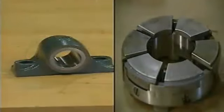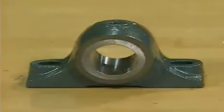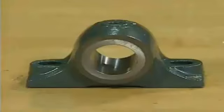Sliding surface bearings are often divided into two basic categories based on the type of load that specific bearings are generally designed to handle. The two categories are journal bearings and thrust bearings. Journal bearings are generally designed to handle radial load, and thrust bearings are generally designed to handle axial load. Let's look at journal bearings first.